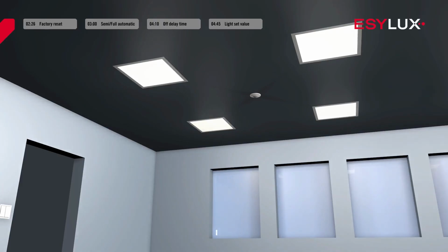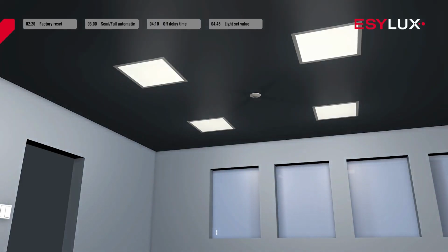If you use lights with additional light sensors, these sensors must be calibrated. Otherwise, the light sensor in the presence detector will be used, provided it is activated. A lux meter is required for calibration. If you do not have a lux meter to hand, you can also adjust the brightness manually. We will start with the more precise option, using a lux meter.